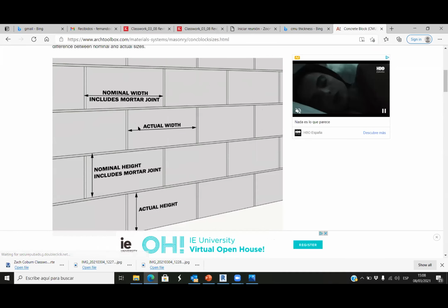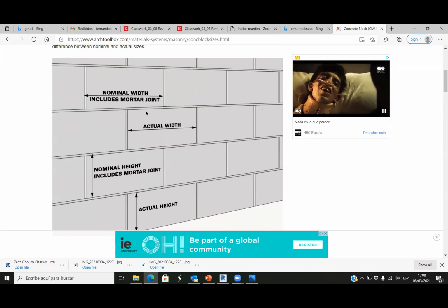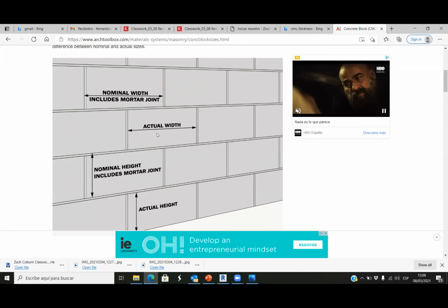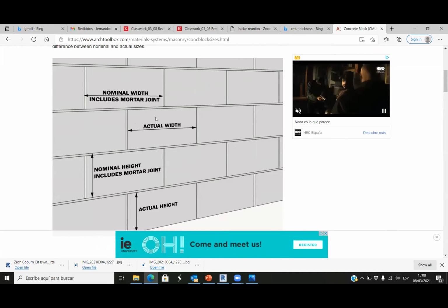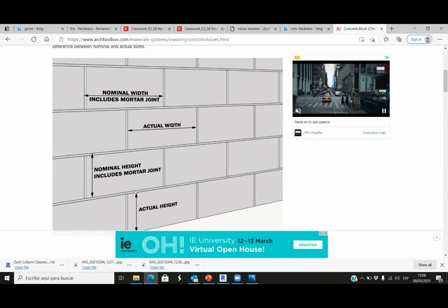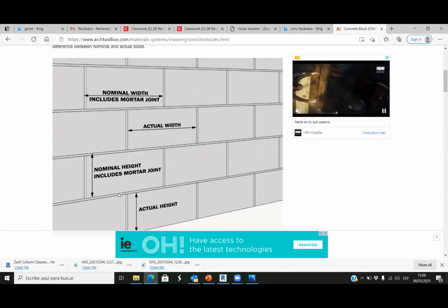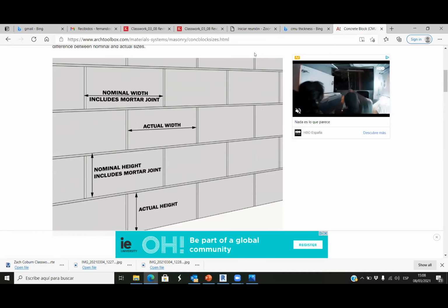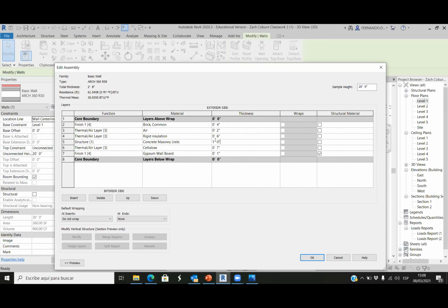So that's it. Okay, so this is the length, which is 16 inches. The height is usually 8. We can have only half a block, so it will be like a square, 8 by 8. And then the dimension that we don't see can be either 4, 6, 8, or 12. Okay, so Zach, you have decided on a foot, so it's 12 inches. That's fine.